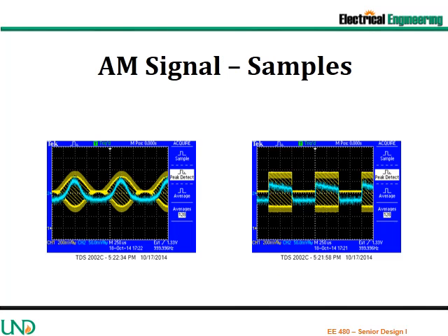The AM carrier signal is set to 1 MHz. This results in a clean demodulated signal. Notice the distortion on the negative half cycle of the output sine wave. The envelope detector also results in distortion of the square wave due to the DC blocking capacitor.